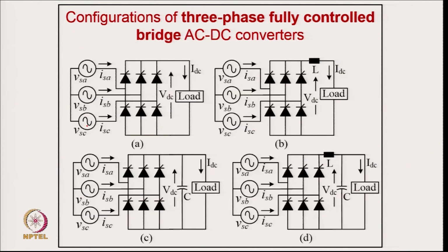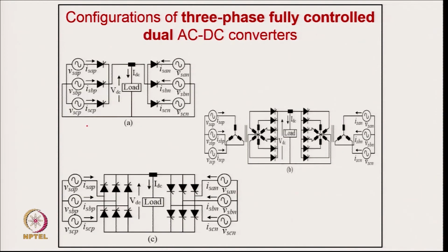And this is a bridge converter. So here also you draw harmonics, and of course, with the firing angle you draw a changing reactive power also. So they are considered quite the worst as far as power quality is concerned.